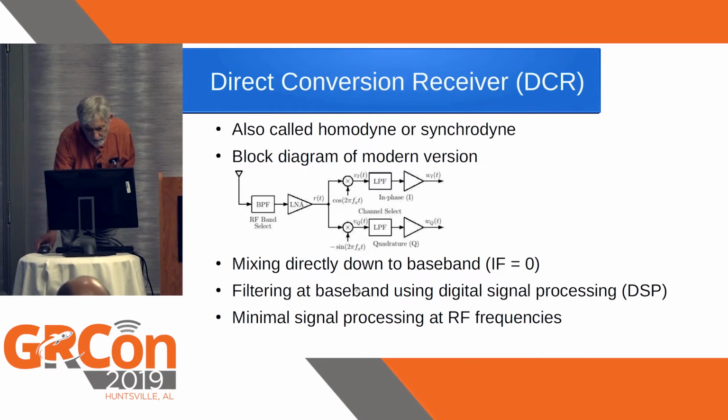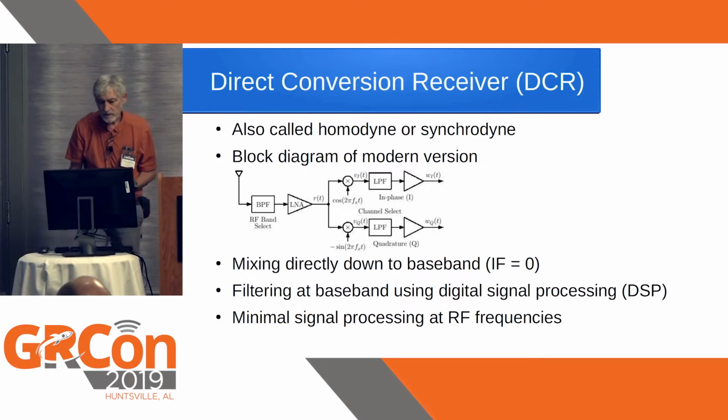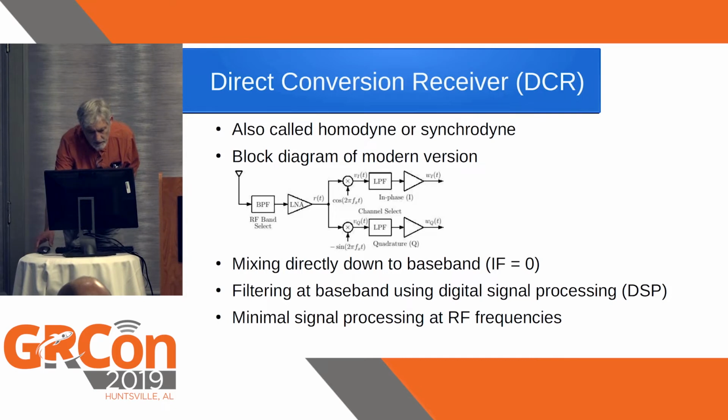You have IF equal to 0, so that means you're not going to have an image frequency. You filter at baseband, typically using digital signal processing, so you don't need any bulky filters at baseband. And you do minimal signal processing at RF frequencies.